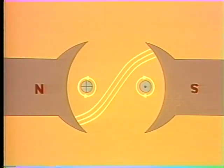As you can see in this cross-section view, the conductor's magnetic field caused the lines of flux in the permanent magnetic field to shift. You can see that the direction of the shift is opposite from the direction in which the conductor is turning. And by the way, the rotating assembly of any DC motor is always called the armature.